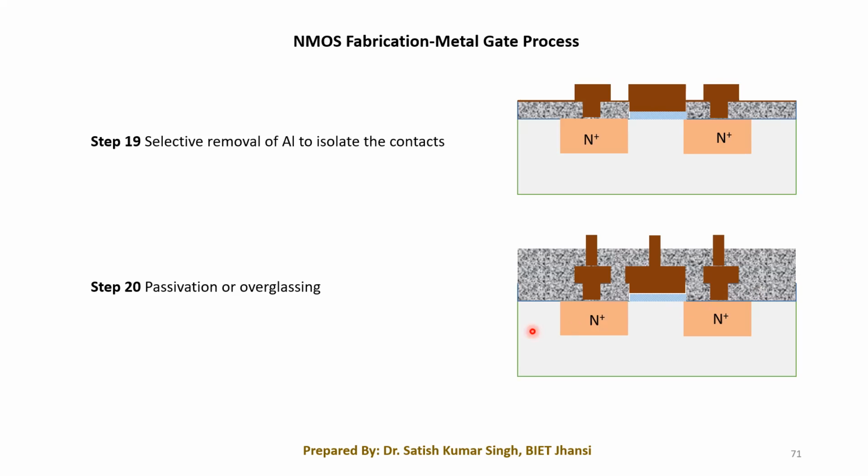If any contamination from chemicals like HF solution, piranha etch, or some organic compound is present on the device, it is going to badly affect our device performance. So we need to understand how we have to remove these contaminants while fabricating the devices.